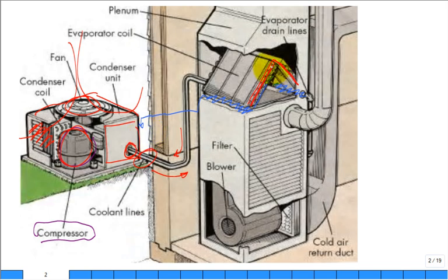And so that's why it's typically shaped like this, or maybe sloped in another way to use gravity. And now we have a fan, a blower motor. It draws air in. Here's a return air. It could be ducted. In a lot of homes, it's not ducted. It's just through the hallways to get to the return air. Put it through a filter. Make sure you keep your filters clean.